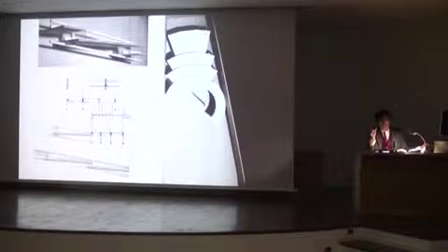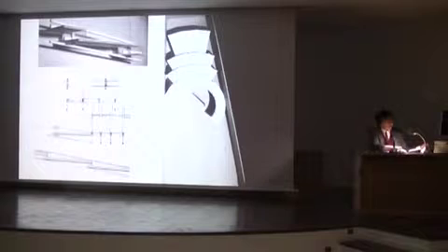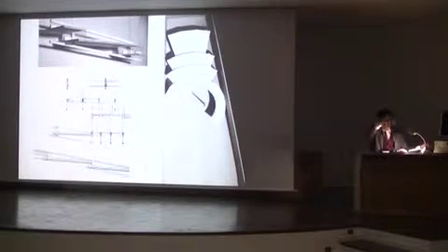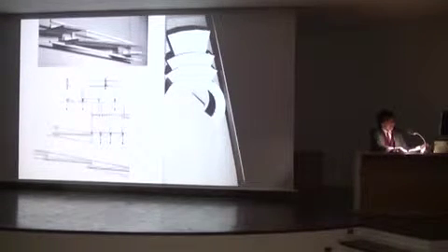This piece here plus the wings, this is a rail of 1 centimeter times 8, and it's solid, welded. It's welded in the inferior part of the omega and in the part here of this tube profile. Sometimes it goes on top, sometimes it's underneath, because the roof is going through there. Here you see that on the model. On this rail you would fix the glass polygonally, directly, closing the distance between each of the roofs.